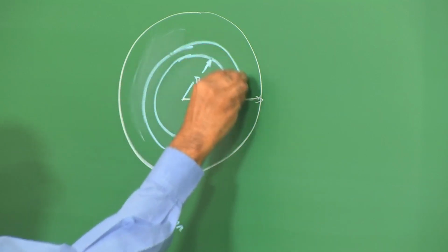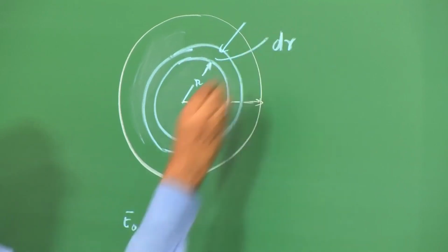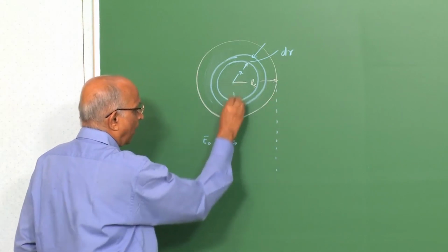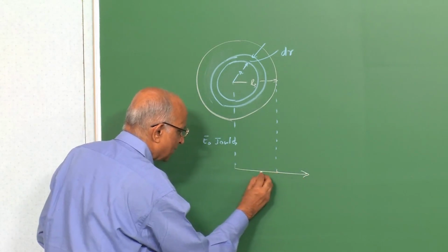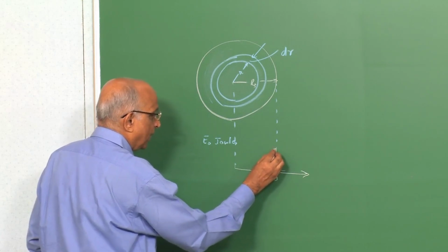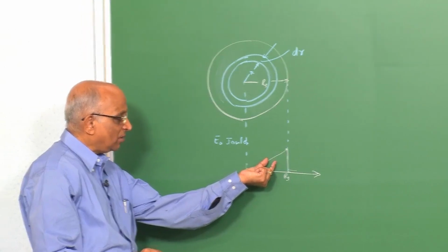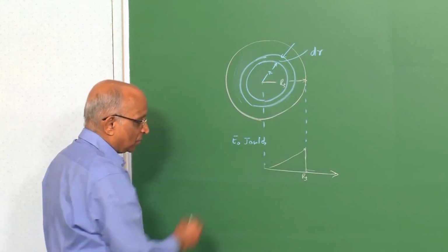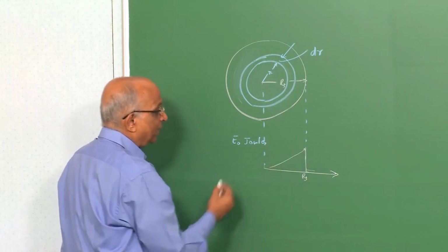and of width, that means I look at a spherical shell of thickness, let us say dr, at a distance r, and now the blast wave is at a distance Rs from the source. Therefore, maybe this is my distance, let us say Rs over here, the initial pressure jumps up over here, and then maybe the thing expands out. We looked at the expansion in the context of the mass conservation, and we found that most of the mass tends to be concentrated at the front, and thereafter there is not much mass left, because all the density is over here. Therefore, there is something like a gradient over here.